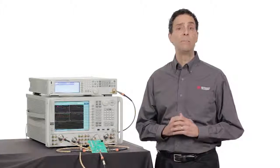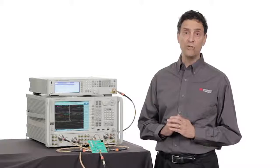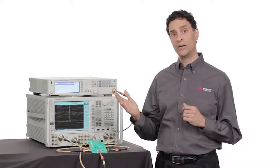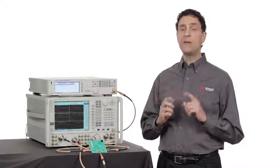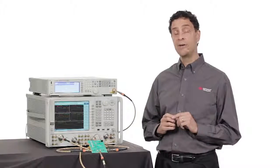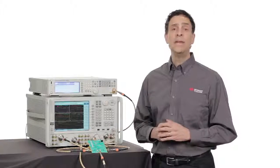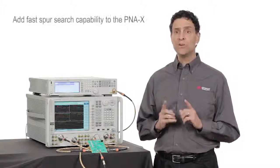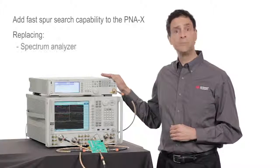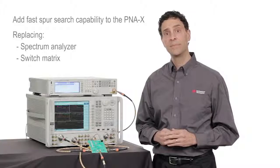These measurements can be performed many times faster compared to those done with the traditional approach using a spectrum analyzer and standalone signal generators. However, a spectrum analyzer remains an essential tool to measure undesired spurious signals coming from the converter. The new PNA option adds fast spur search capability to the PNA-X, replacing a standalone spectrum analyzer and switch matrix in your test systems.